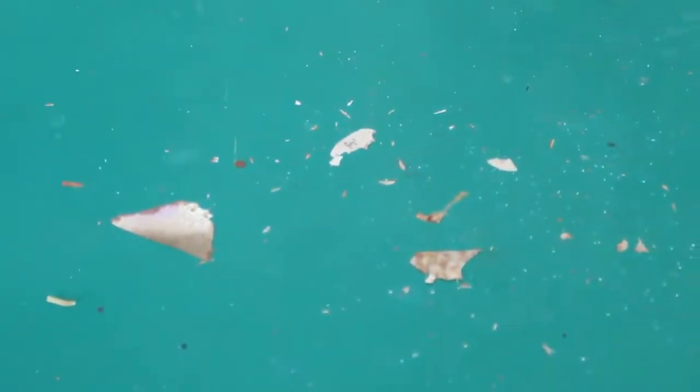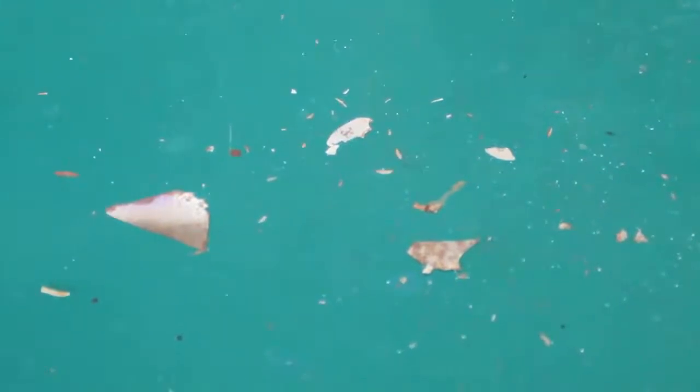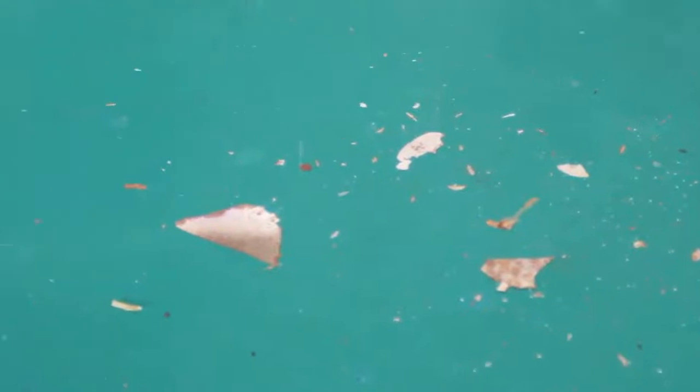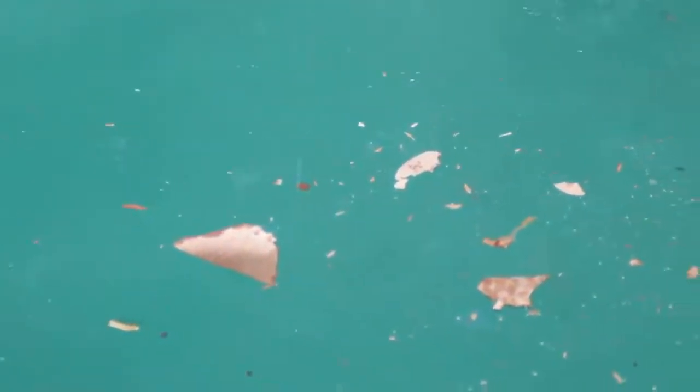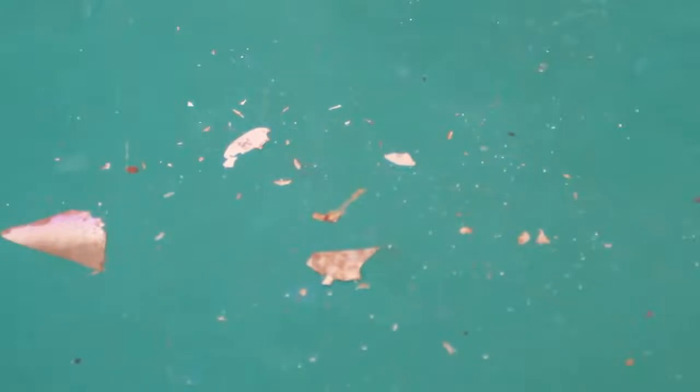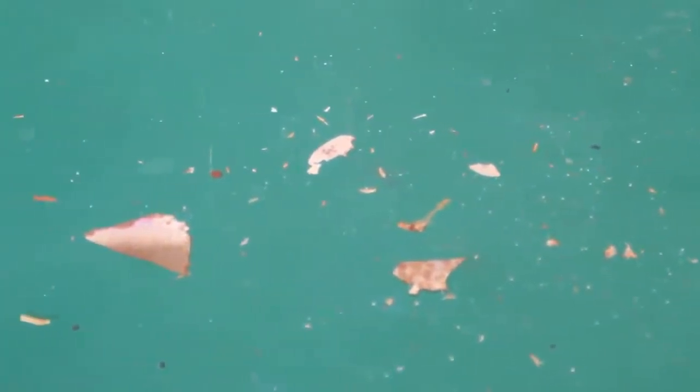Just on that, I don't know if you can see that there. This is the mess that the matte glass cores sometimes make. When you're putting them together, they peel off. That's what I was talking about in the last video. Hopefully you can see that alright. Some of them are very sharp, some of them are very small, and if they do get into your skin, they are very, very hard to get out. So please be careful. It's not a very nice thing to deal with.